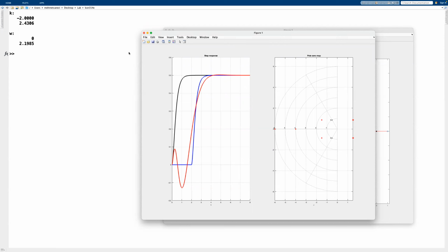But you can claim something else, which is quite interesting to note. You can basically claim the instability interval. What I mean by that is that if the Padé approximation is stable in this interval, out of this interval, it's not going to be stable, and the system is also not going to be stable for sure. So between -infinity and -2, the original system is also not stable.